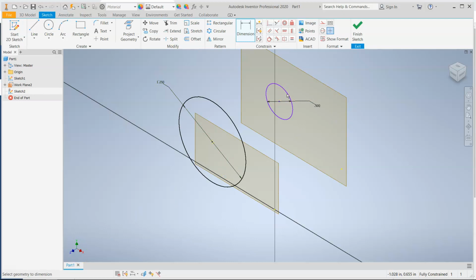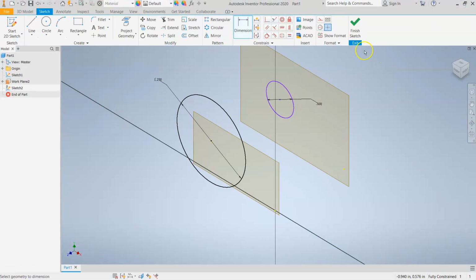into a cylinder. This time we're going to connect these two circles, and the part is going to connect between them and gradually get larger and larger as it goes from the small circle to the large circle. This is called lofting, when you change size and or change shape as it extrudes. So we're creating a loft. So let's see how this works.